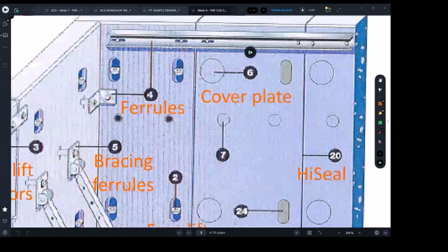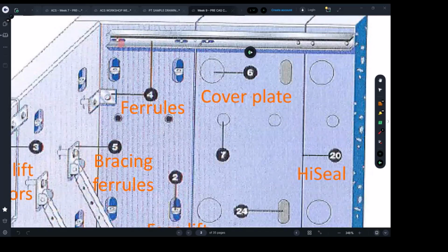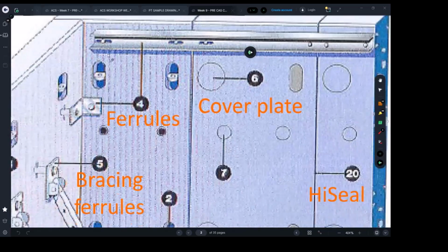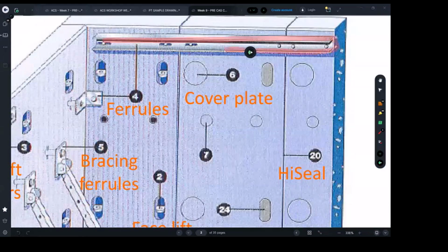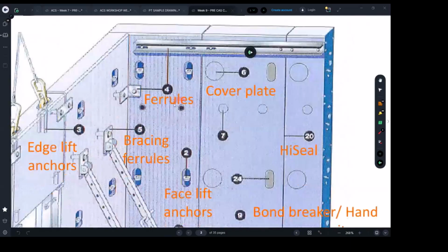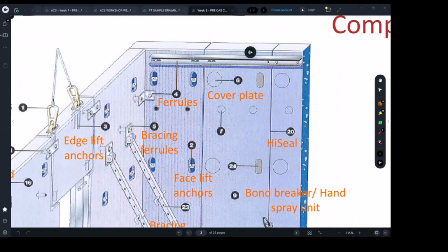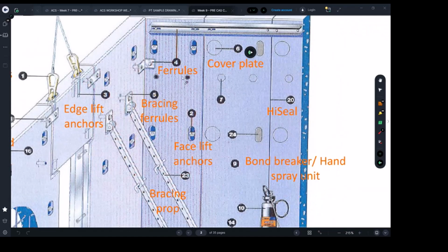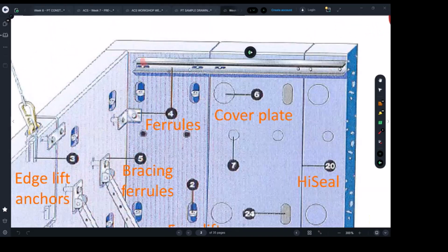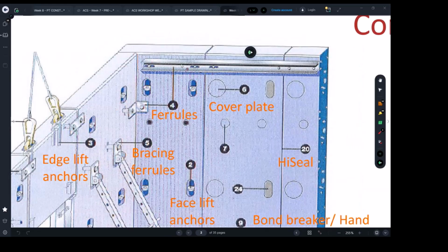So you can see sometimes the ferrules, as what we have here. We have also ferrules here used to allow for installing a steel tie. This steel tie is used for permanent consideration. So again, whether the ferrules or the propping ferrules, or the end anchors, they are just components which are temporarily used just for lifting or temporary propping of the panel. But these ferrules here are permanently used to tie the panels together and allow for constructing the roof